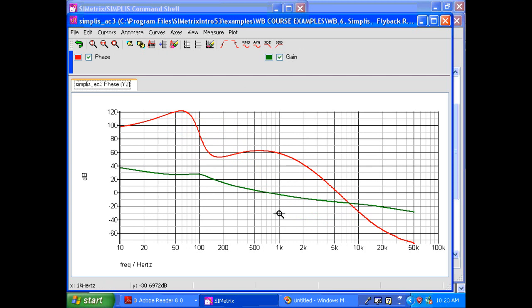Now that's a better curve, but you'll notice where we're crossing over. It's only about 700 or so hertz. The reason for that's because of the right half plane, which introduces considerable phase shift. Now we're actually going to show that to you.